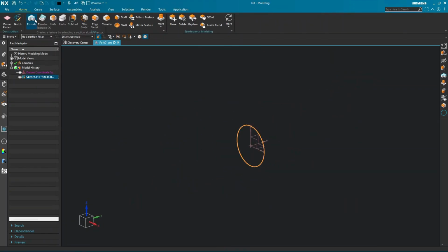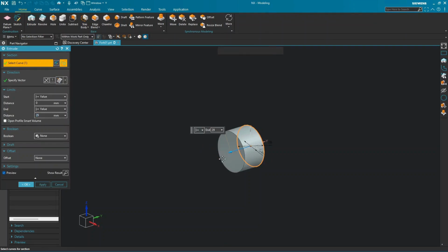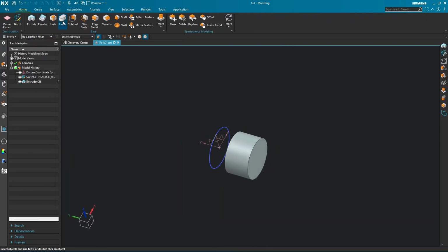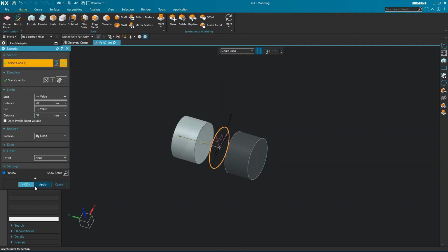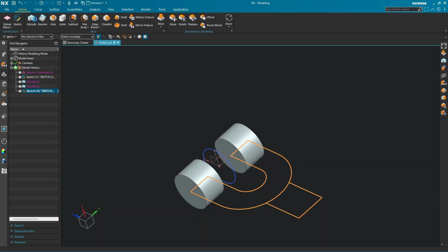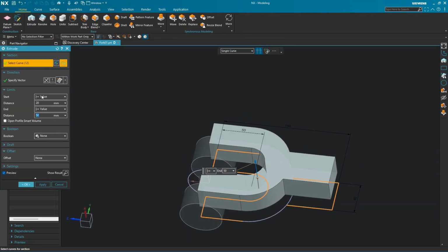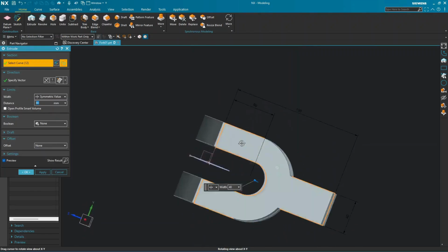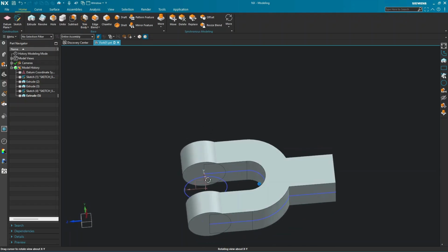Let's begin our modeling with the fork end, which serves as the base connection for the knuckle joint. I start by creating two equispaced circular extrudes. These represent the fork arms in which the knuckle pin will be inserted. The spacing between these two arms is carefully maintained to ensure proper clearance for the eye end. Once the arms are ready, I connect them using a Y-shaped body, forming the main fork structure. This ensures strength and smooth load transfer between the arms and the shaft connection.